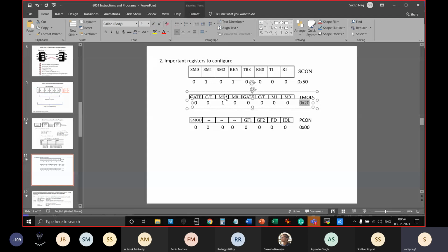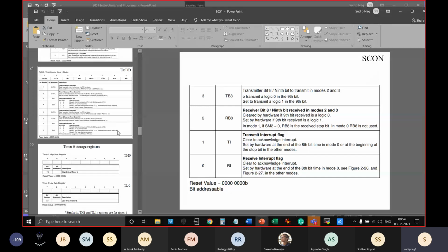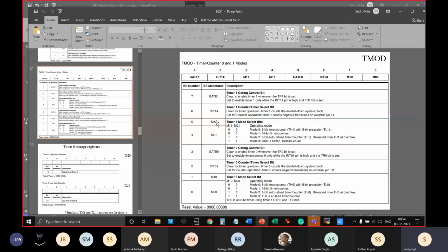For timer 1, in auto reload mode, as I said, there is a hardware restriction: only TH1 should be used, and it is automatically reloaded with the original value of TH1 once you get an overflow condition. You upload the count value in TH, and the counting happens in TL. TH is just a storehouse, and once counting starts, TH gets copied into TL.